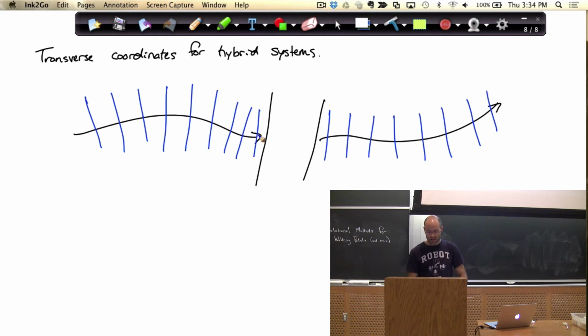It turns out if I can write down a Lyapunov function in transverse coordinates where the transverse sections never intersect with the surface, then I can use all the same tools, where I now solve a jump differential equation. My Lyapunov equation that I'm going to simulate backwards is smooth here, and then for one step I solve the discrete time differential equation, and then I simulate backwards here.